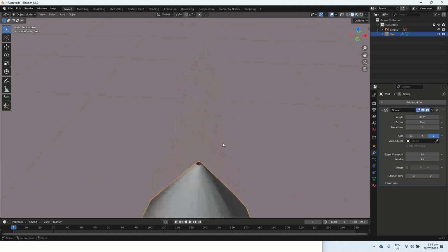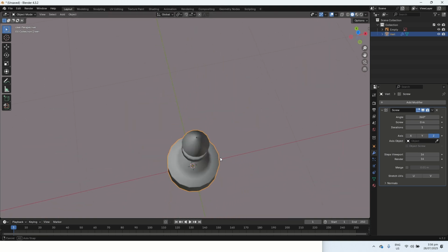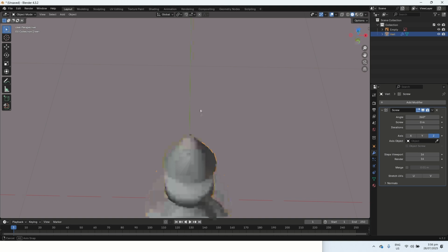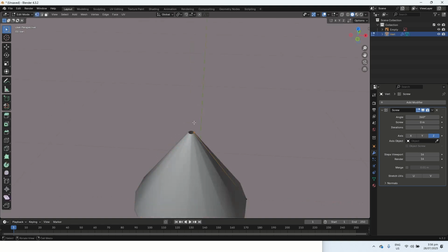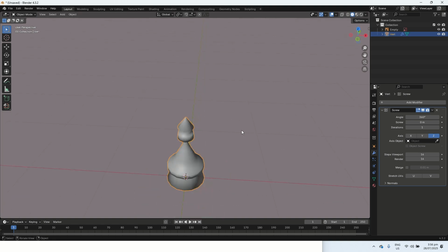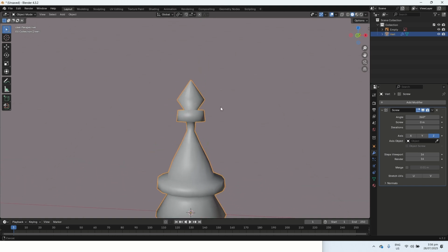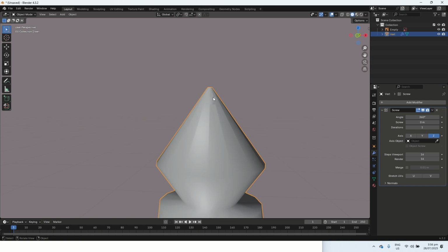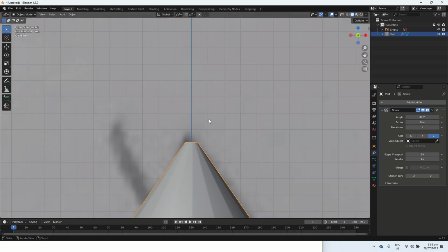So I will once again mention that at the very top here, I do have an opening. So this is currently not a closed shape. We would fix the problem, or we could move the middle point to being directly on the center line. I am actually going to leave it like this for now, just so that when I demonstrate my Booleans, you'll see what not to do, okay? Because open shapes like this don't Boolean correctly. So I will show you how to do it for now, and then I'll revert to this.